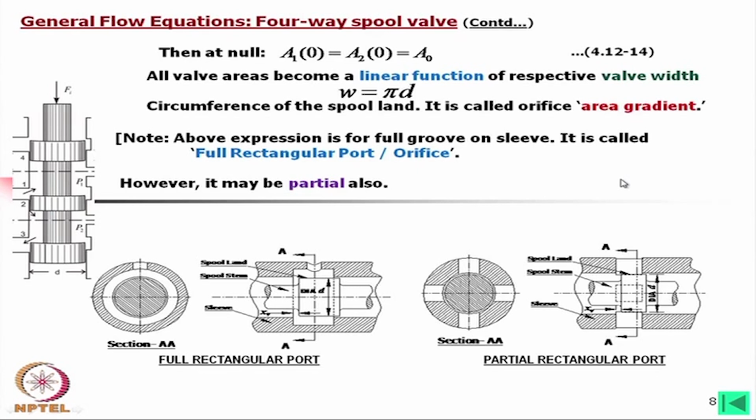In that case, for the partial groove we will consider the number of holes into this width as the total width, and the coefficient of discharge is more or less the same in all cases. Okay, am I clear on this part, that these are widely used in these control valves instead of the full port.